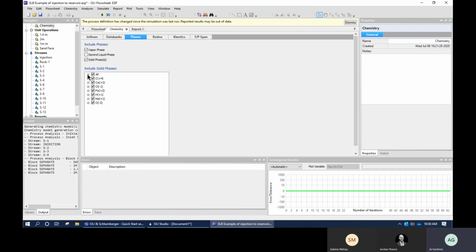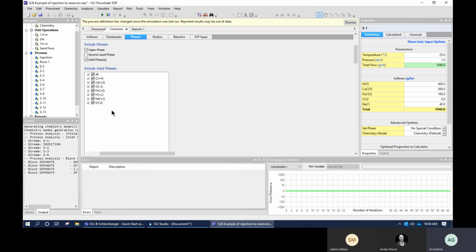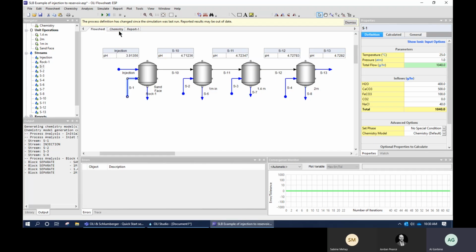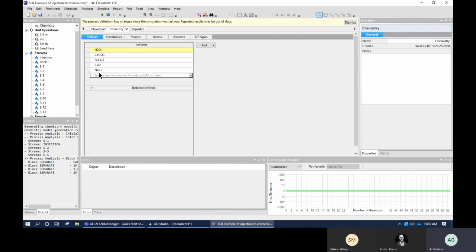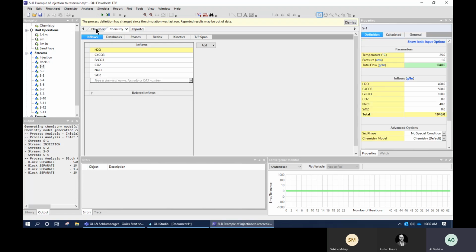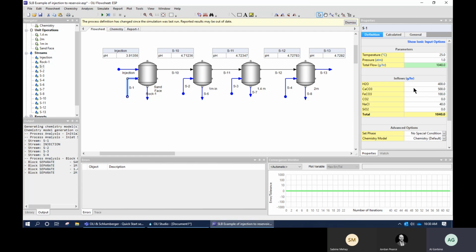Now, let me jump back here real quick. Now that I've got my geochemical database in, I'm going to add quartz, because this is really where it gets interesting. If I go back to my flow sheet and go back to my solids, I added a lot of cementation material. But now I'm going to say it's about 90% silica. So let's say I've got 500, 600 grams of rock. I'm going to say it's 540. That's 90%. And then I'm going to make this 50 and that 10.